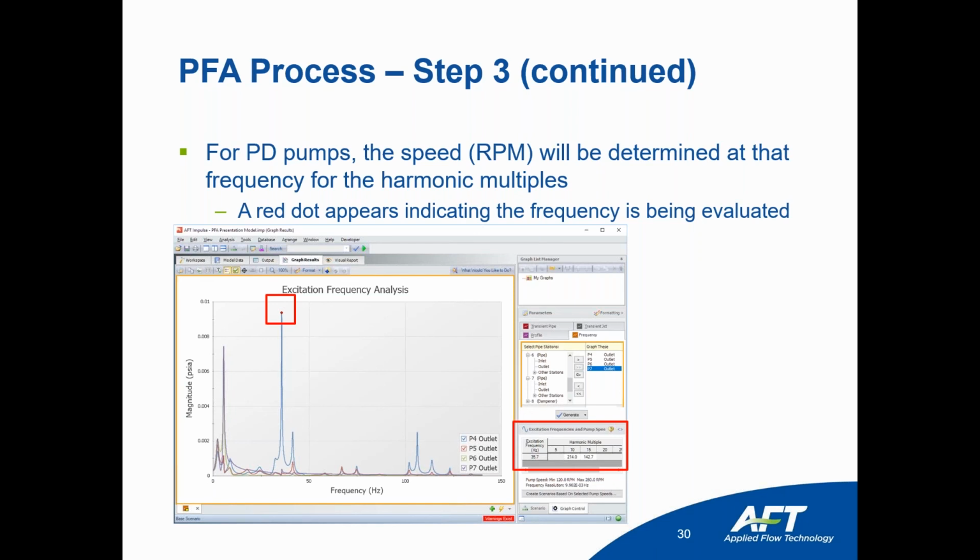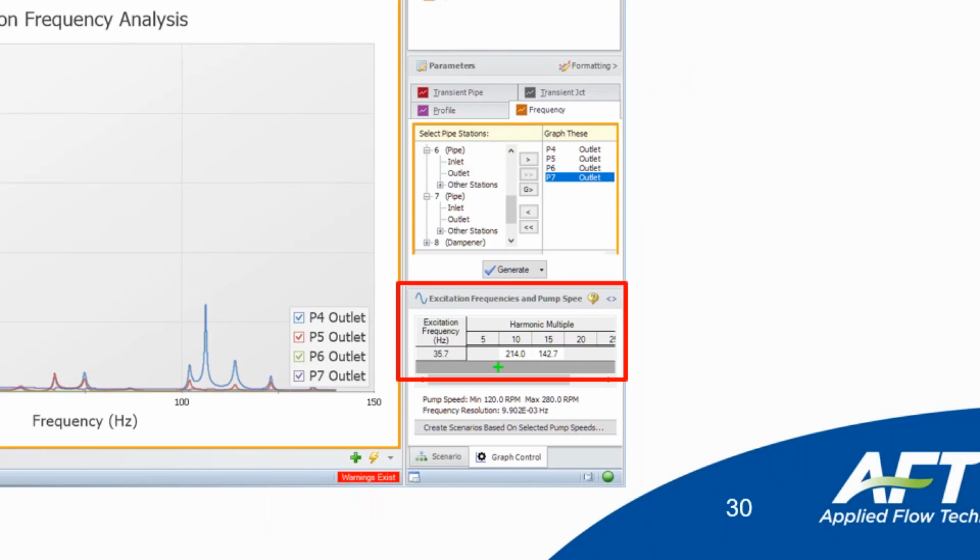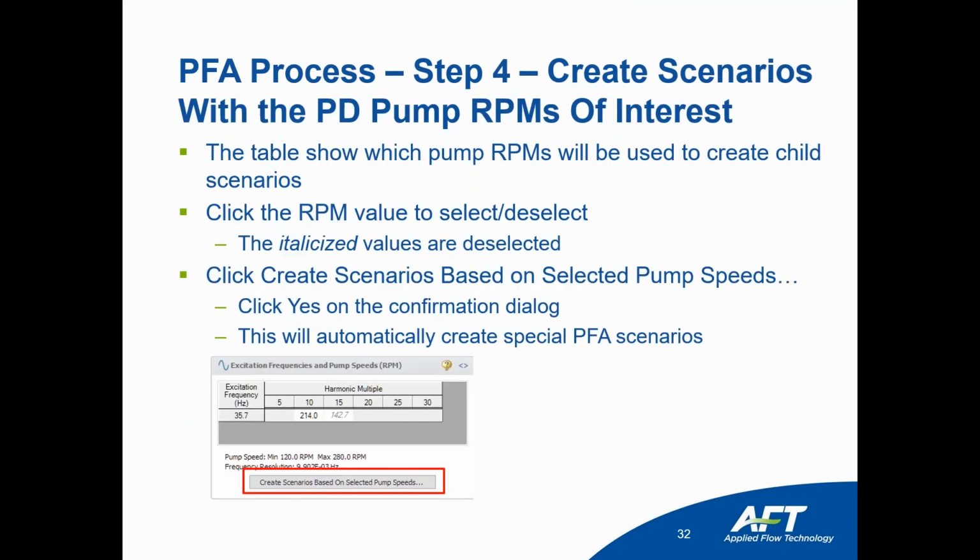So once we do that, we select the range of frequency with the largest pressure, and left click and hold while dragging the mouse cursor, and the range selector will appear on the graph. The range selector will determine the maximum value inside of the selection. When the mouse button is released, the frequencies where the maximum pressure magnitude is located are pointed out using the annotation.